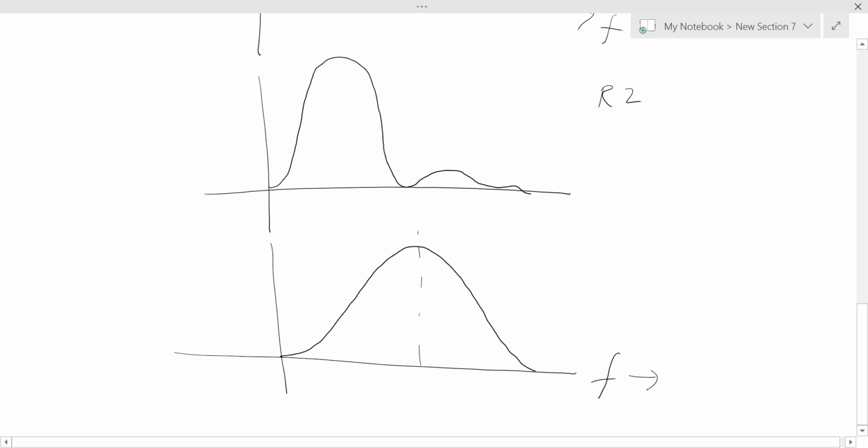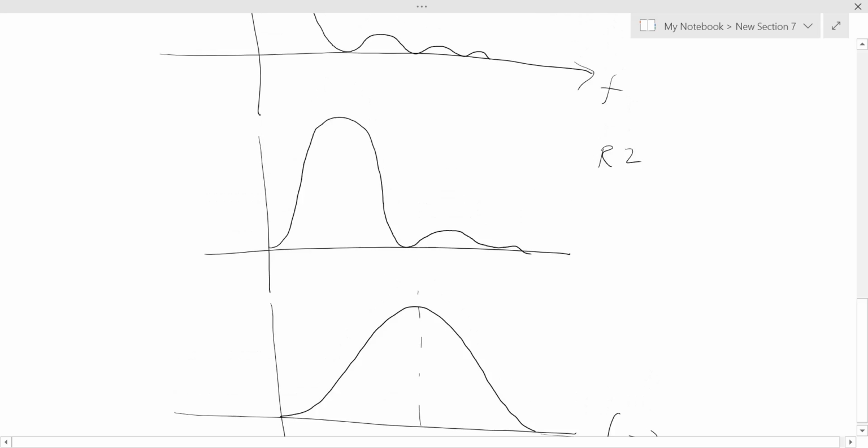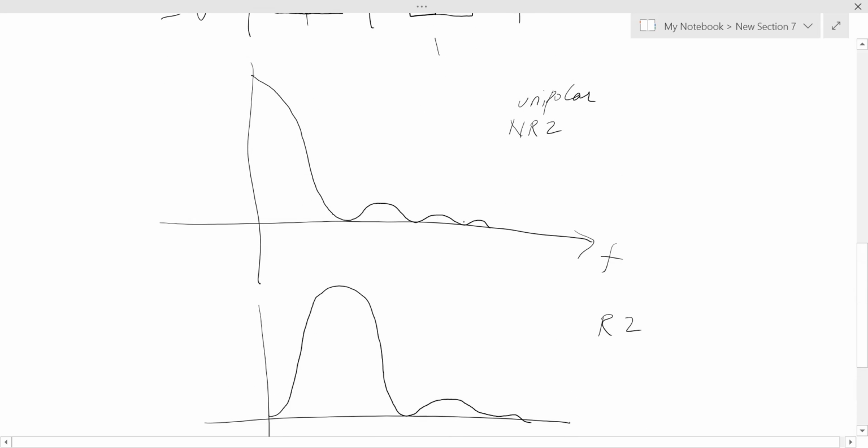So we see that Manchester line codes don't have too many side lobes, whereas non-return to zero has side lobes also. So it is not an efficient use of bandwidth. This is one important factor when you convert your pulse code modulation bits into some line codes. So we have to decide which line code we have to use. Although in wireless communication it doesn't affect too much, when you have to communicate over LAN or other, it affects.